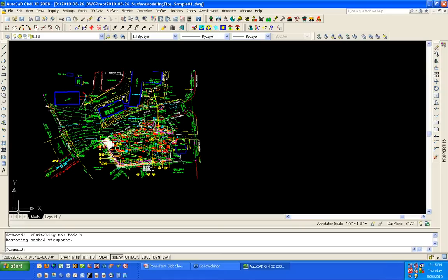So if that's really new to people, on my website, on the support page, I have actually got under the AutoCAD handouts, there's actually one called Drawing Orientation that goes through UCS rotation, D-view twisting. There's a couple of methods, so you can learn a little bit more about that and kind of see if that little square's not there, what else might you do. So, I believe at this point that we are oriented properly. North is north.